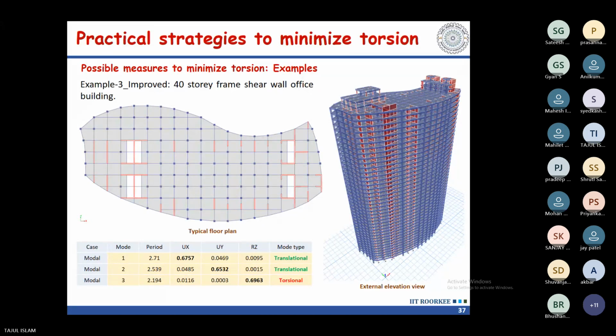Yes, correct. The easiest way is to split the towers at the corridor level, like a cantilever-type corridor. You can provide half from this tower and half from another tower. Split it. Practically, it is not acceptable to the developers. No, this is the easiest thing to do. I don't know why they will not accept it. Cantilever means expansion joints will be created, which creates a leakage problem, and from a serviceability point of view, they will not accept it. Yes, maybe different restrictions are there.